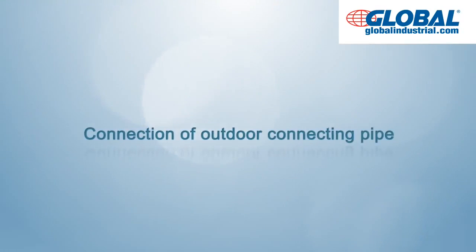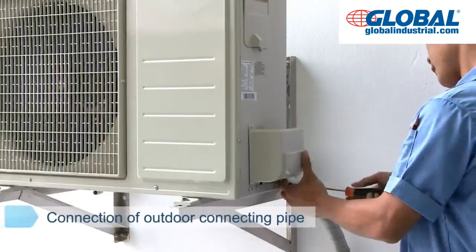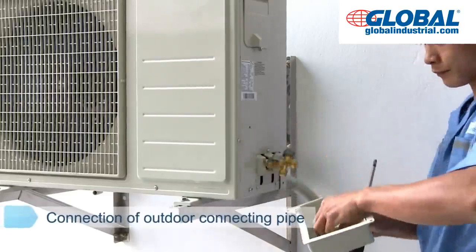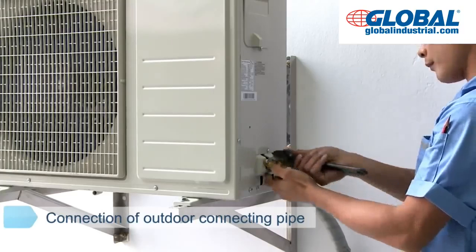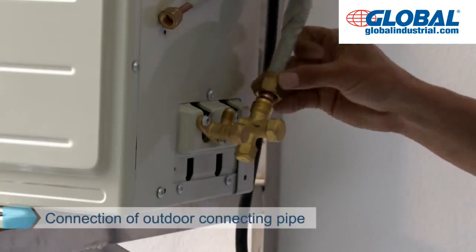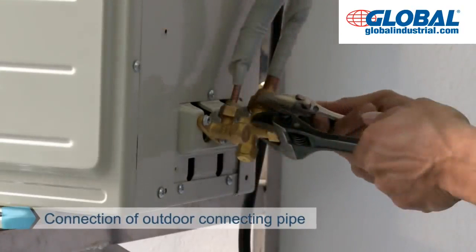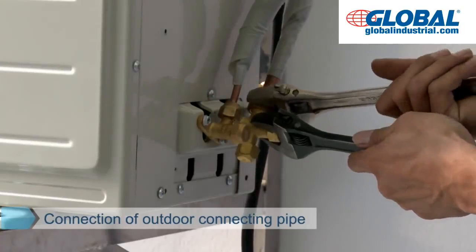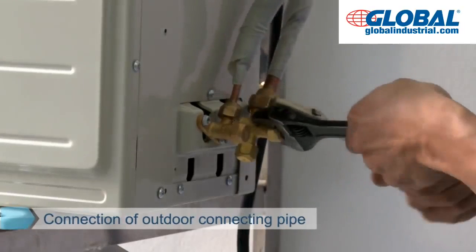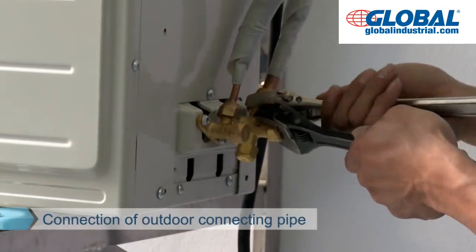Connection of outdoor connecting pipe. Open the cover of water outlet. Unscrew the pipe cap. Align pipe socket of connecting pipe with the bell of globe valve pipe adapter. Screw pipe socket nut to the bottom of globe valve bolt with hand. Then tighten it with wrench. Tighten back after tightening for further tightening.